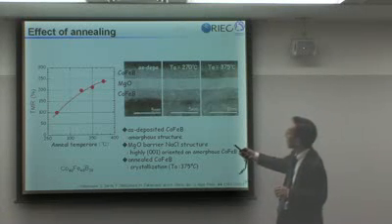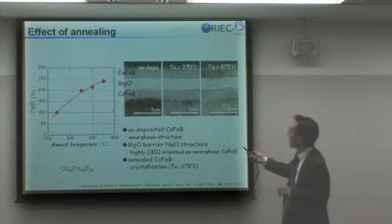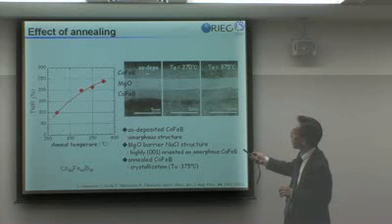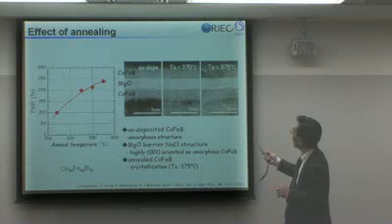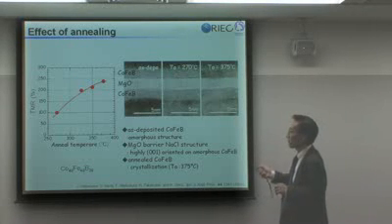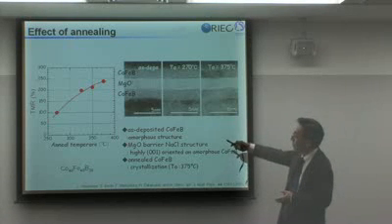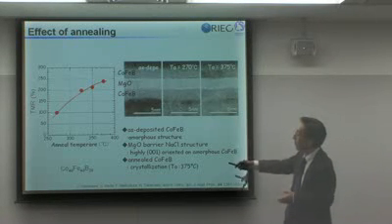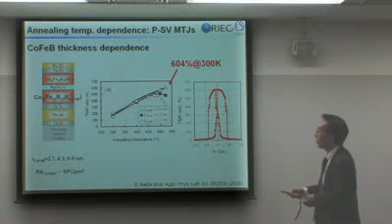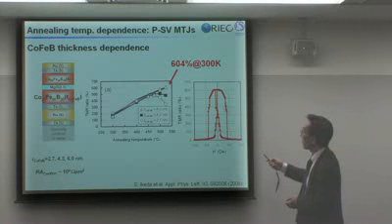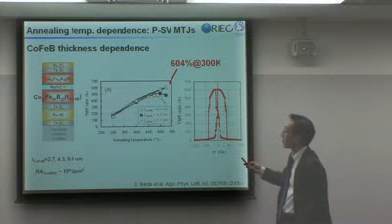And if you anneal it, solid state epitaxy takes place, which means that this amorphous cobalt iron boron crystallizes from this boundary, and eventually at high temperature it crystallizes in the structure that you wanted to have. And you can see that along with this crystallization, the TMR ratio increases. This is how we achieved the highest single barrier MTJ value to date.